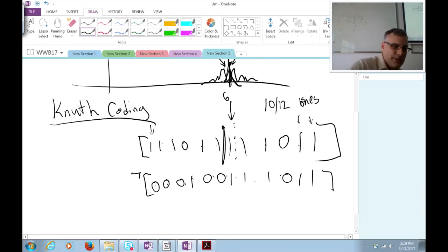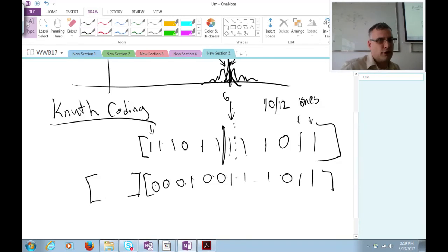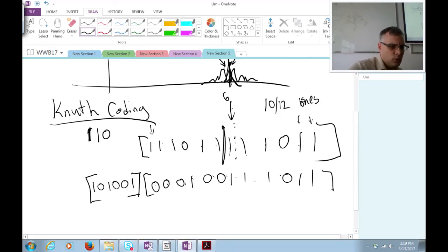And then what I can do is use Manchester encoding to encode that same number up on the front. So the number 6 in binary would be 1, 1, 0, and Manchester encoded that'd be 1, 0, 1, 0, 0, 1. So look, I added redundancy just like any good coding would do.